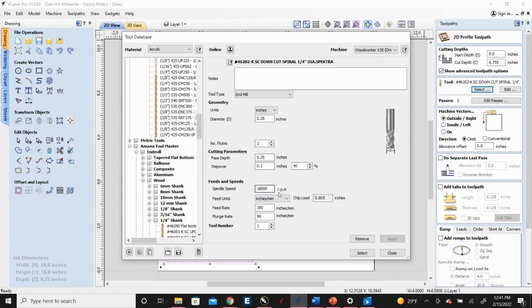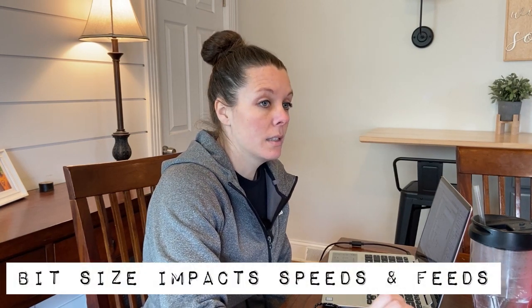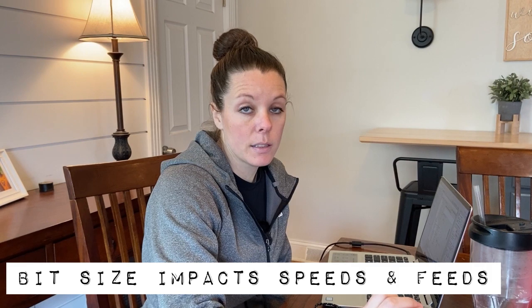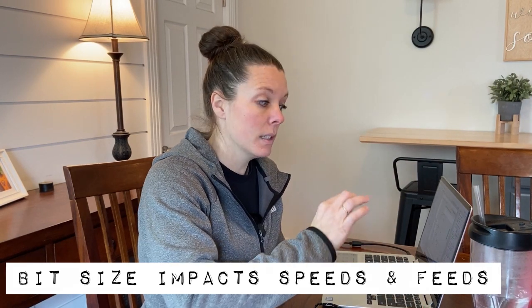18,000 RPM, that's a good thing to take note of. I think a lot of bits do run at that speed, at least a lot of 1/4 inch bits, but the size of the bit is going to impact the speed it should run at. And that speed is talking about the actual speed dial on the router, which goes from 1 to 6. So you're like, well, what the heck is 18,000 RPM then on a 1 to 6 scale? You can Google that simple chart just to keep in your work area so you know. From my research, I believe 18,000 RPM is somewhere between the 3 and the 3.5 setting on your router.